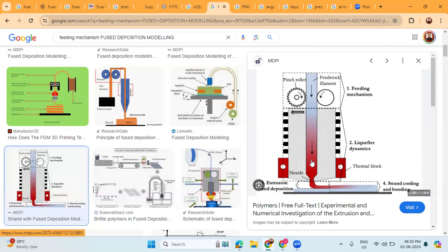Because the melted material sticks to the heating and nozzle surfaces, it undergoes shear deformation as it flows. Thermoplastic materials used in FDM currently show shear thinning behavior, meaning that their viscosity decreases as the shear rate increases. For modeling FDM melts, it is reasonable to use a power law for generalized Newtonian fluids to represent polymers like ABS.